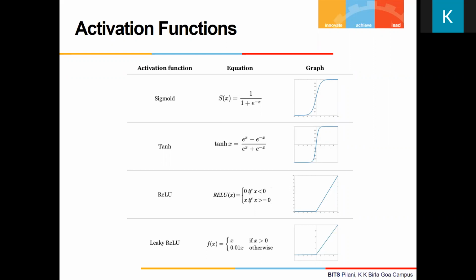So say 100. Based on this, I can find out what is the largest number that is going to come. I will take the worst case. I will say my input is 1, and every weight is the largest weight I got after training. How many inputs are going to a neuron? I know, because that's how we design the neural net, say like 100. So in the worst case, this weight times this input gets accumulated 100 times.